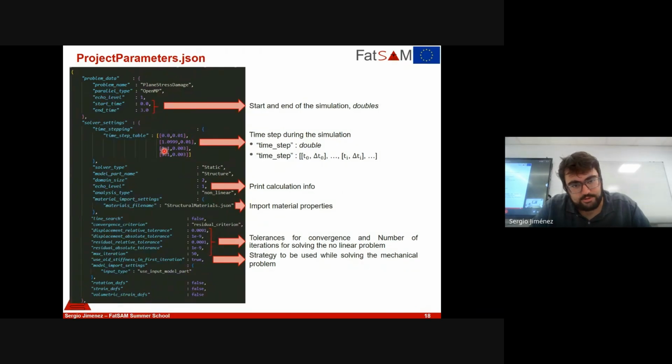And from that point on, basically what I'm setting are ranges for which the time step will be that specific value. My question is, if I define, for example, not 0.01, but 0.03, it most likely would not match 1.099. It doesn't matter. No, it doesn't matter, because basically how it works is it looks for which is the time step to be applied.